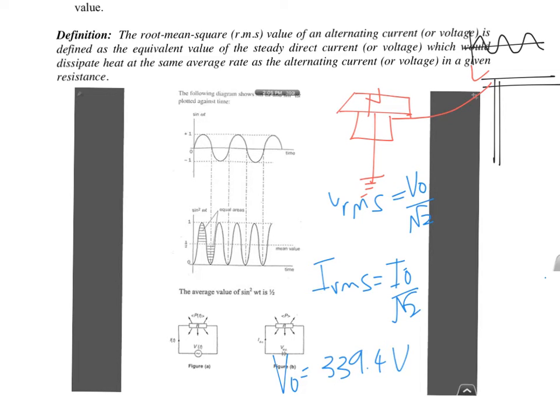Then there's another disadvantage of AC. Some appliances or some electronic components may need DC because they cannot work on AC, so then you will have to have extra circuitry to produce rectification, which is to convert your AC to DC. Because not every electrical component or electrical appliance can run on AC. Example, your handphone charger. If your handphone charger runs on AC, then you will never get charged, because it will charge, discharge, because it flows both ways. So then you've got to convert to DC. Some electronic components in your TV as well, they have to convert into DC. So you have extra circuitry there.